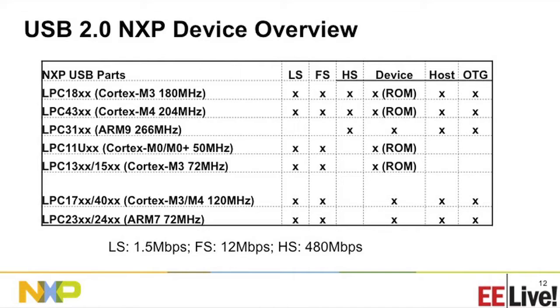So you have a couple of choices. Am I host or am I device? I'm typically a device if I'm connecting to the PC. But I might be host if I want to plug a memory stick in or I have some other connectivity. Here on our chart of micros, these are all NXP micros. If it starts with an LPC, that's our convention for one of our microcontrollers. The 11U is a Cortex-M0 running at 50 megahertz. You have low speed, full speed, and we're device only, with drivers in ROM. So that's a mouse or other sort of device connectivity.